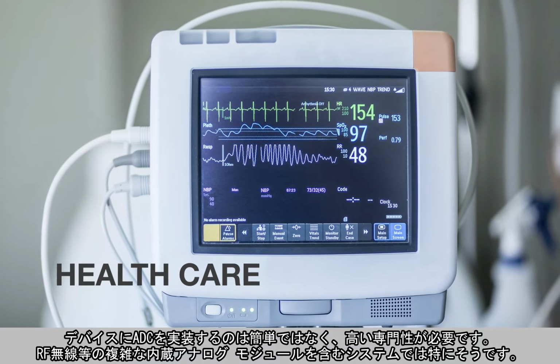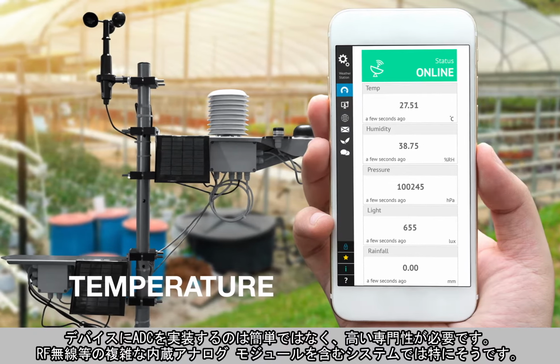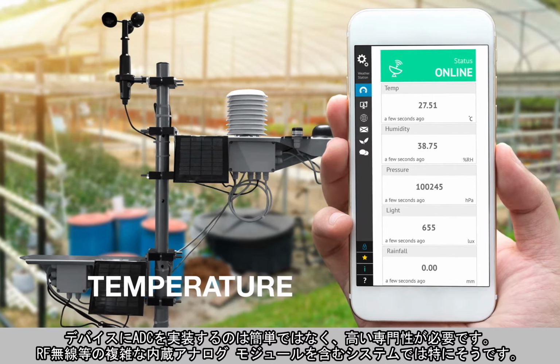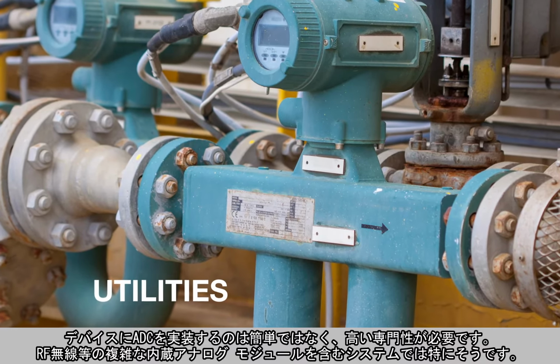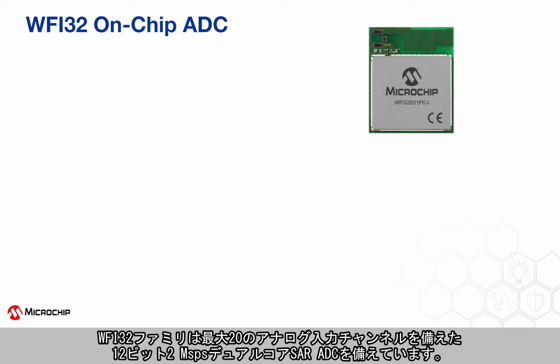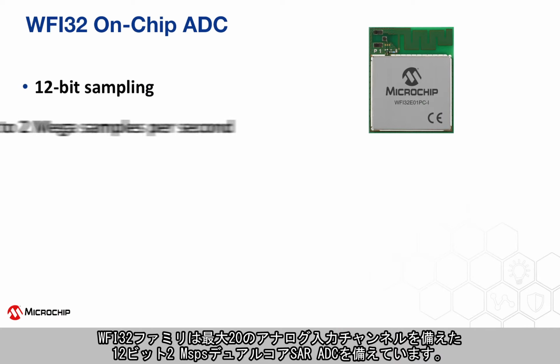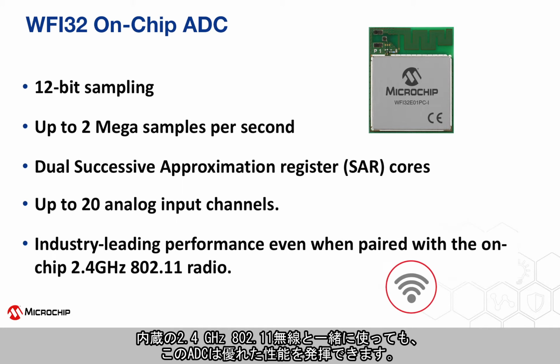Due to the intricate design characteristics of an ADC implementation in silicon, it takes much expertise to get it right, especially on systems where there are complex, on-chip analog peripherals like RF radios. The WFI32 device family comes with a power-packed 12-bit 2 Msps dual-core SAR ADC with up to 20 analog input channels. Even when paired with the on-chip 2.4 GHz 802.11 radio, this ADC showcases excellent, industry-leading performance.